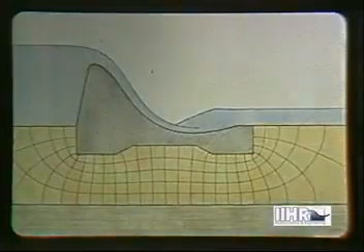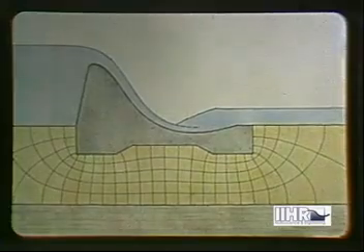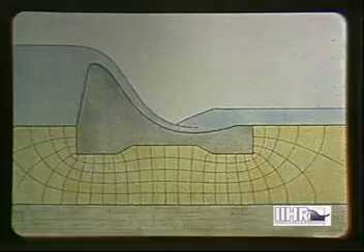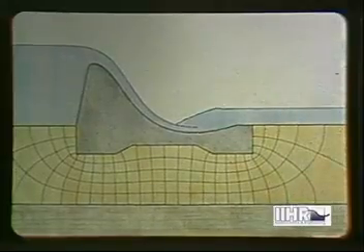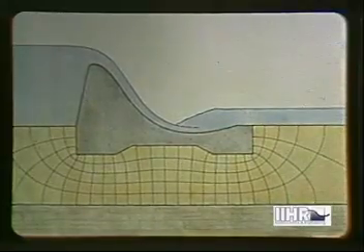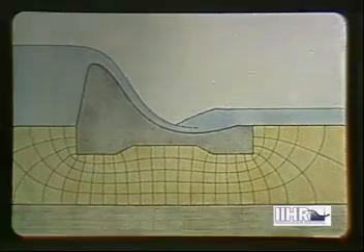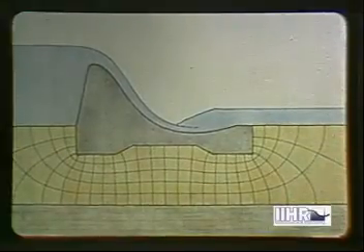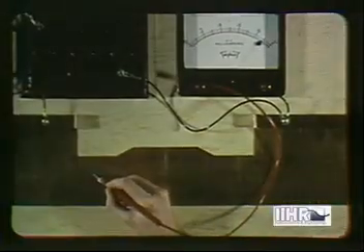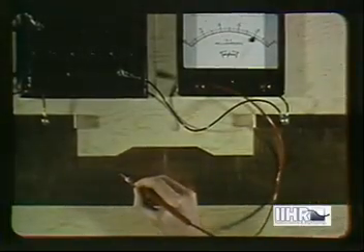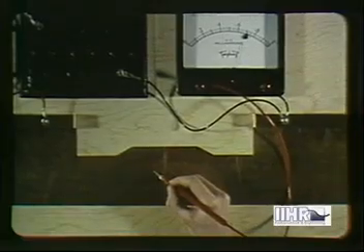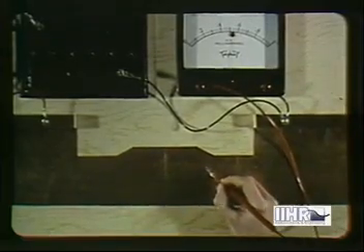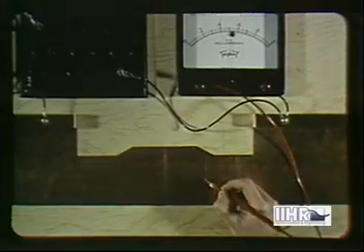It is of interest to note the percolation of either a liquid or a gas through a permeable material, like the earth below a dam, will also be indicated by a flow net if the material is of the same porosity in all directions at all points. Moreover, the same net will correspond to the flow of an electrical current through a conductor, the voltage varying at a maximum rate along a streamline, but remaining constant along a normal line.